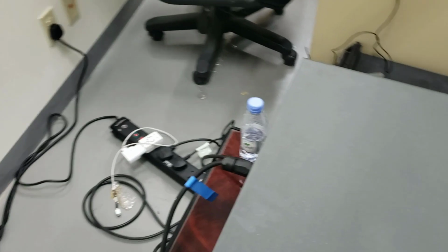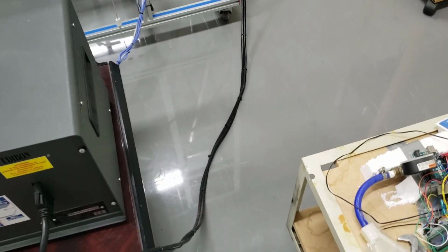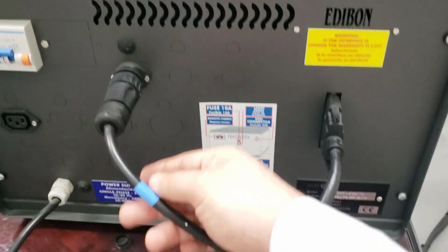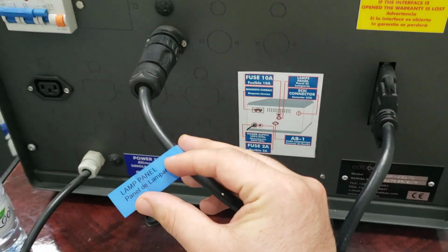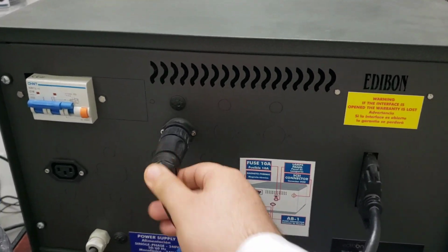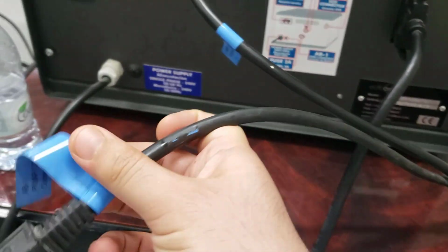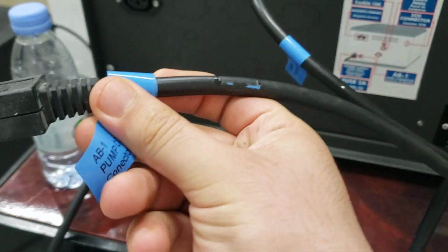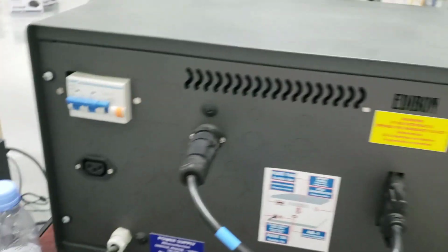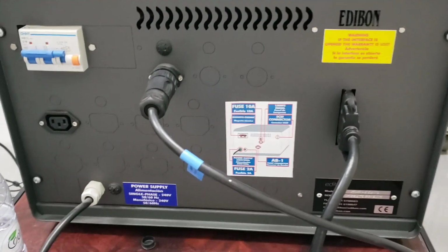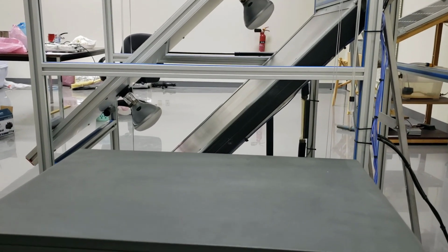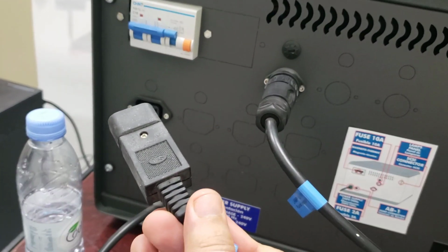And also this black wire should be plugged in here. For example, this is the lamp panel. This is the wire for these 2 lamps, so it should be plugged in here. And this is the wire for the pump, so it should be plugged in here. If you want to operate the system in thermosiphon mode, this wire should not be plugged in. If you want to operate the system in active mode, we should plug in this wire.